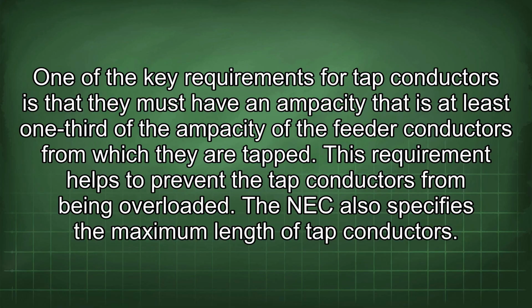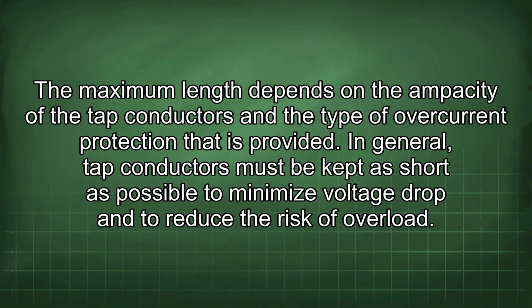This requirement helps to prevent the tap conductors from being overloaded. The NEC also specifies the maximum length of tap conductors. The maximum length depends on the ampacity of the tap conductors and the type of overcurrent protection that is provided. In general, tap conductors must be kept as short as possible to minimize voltage drop and to reduce the risk